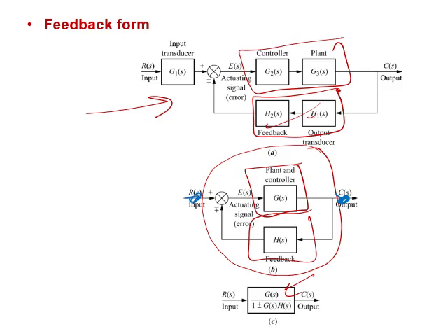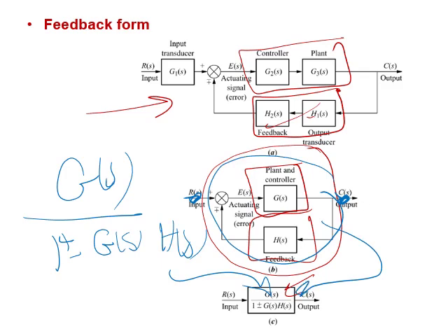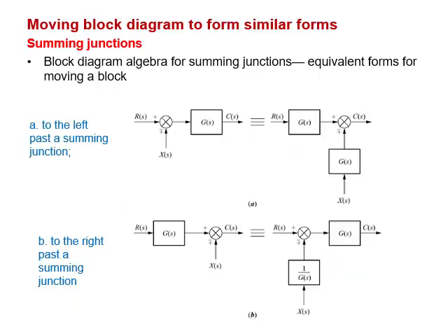In between them, what do I have? It's a feedback system. I hope you remember it. We will find that the transfer function can be written as G(s), which is the feed forward, over 1 opposite sign, I hope you remember, plus or minus, feed forward times feedback. That's how we can simplify it. So instead of having this arrangement, we can simplify it to be this block.